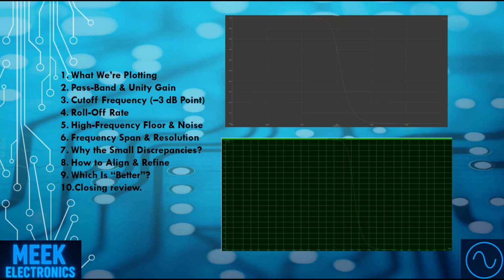Closing review. In summary, you've got a unity gain, 1.06 MHz cutoff, 20 dB per decade RC low-pass in both packages. Any small shifts are just default setting quirks. Tweak your sweeps, match units, and you'll see perfect overlap.